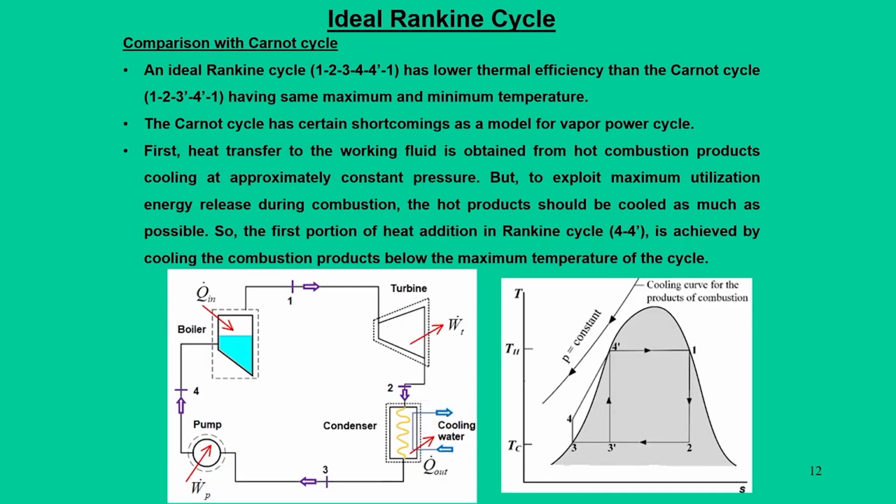Then we will move on to, now that we have idealized the pump work, let us see how this Rankine cycle gets compared with respect to Carnot cycles in terms of performance calculations. First, I have already told that the work ratio or work output for the Rankine cycle is higher, but the thermal efficiency is lower in comparison with the Carnot cycle.